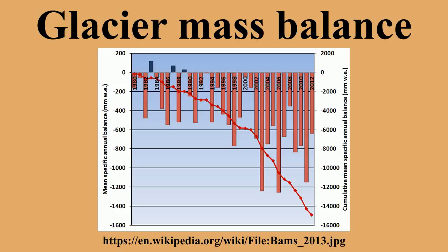In temperate glaciers, the insertion resistance of a probe increases abruptly when its tip reaches ice that was formed the previous year. The probe depth is a measure of the net accumulation above that layer. Snow pits dug through the past winter's residual snowpack are used to determine the snowpack depth and density. The snowpack's mass balance is the product of density and depth.